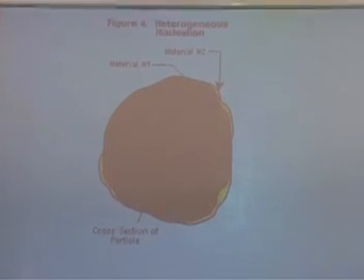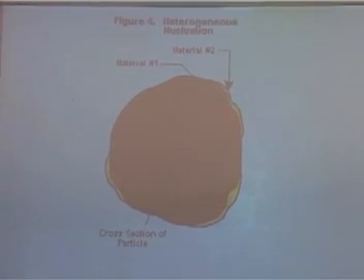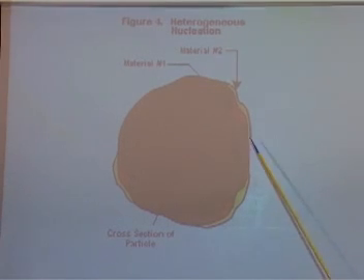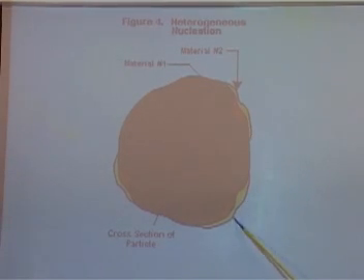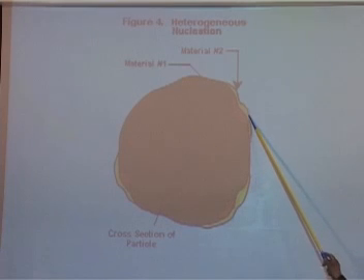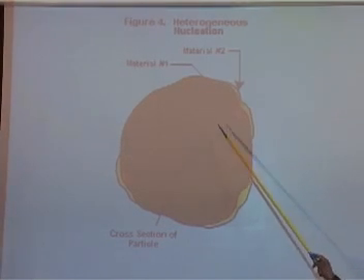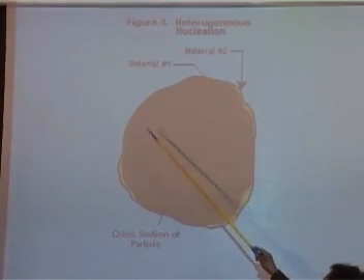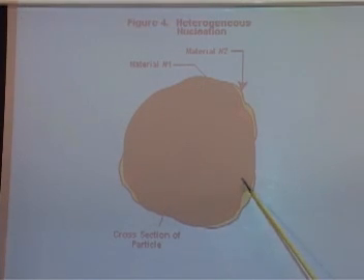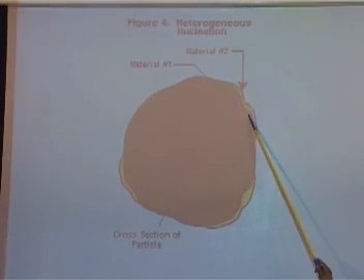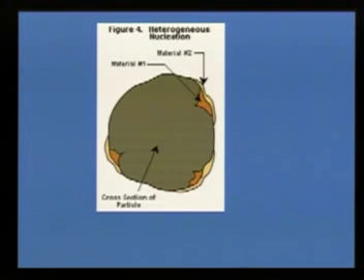There are two kinds of nucleation. One is heterogeneous nucleation and one is homogeneous nucleation. For heterogeneous nucleation you need already some parent particle on which the nucleation of your vapors, that is your material 1, should occur. And if you don't have the material 2, then homogeneous nucleation can occur. For homogeneous nucleation to occur, the supersaturation level has to be way high, otherwise that won't happen.